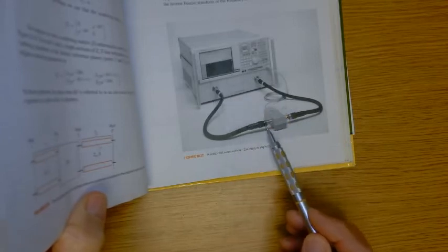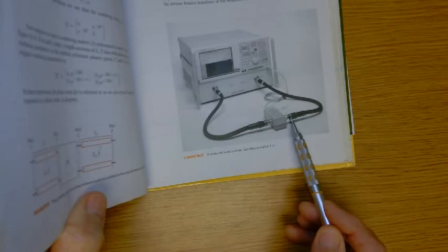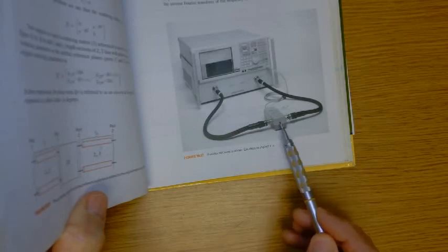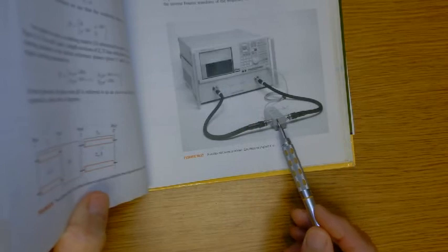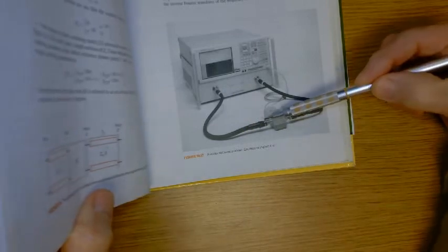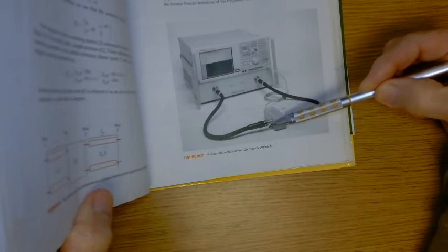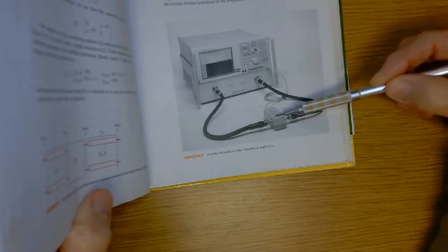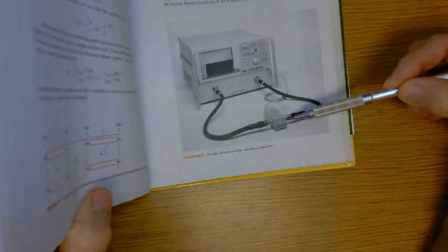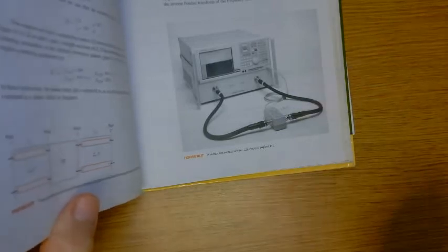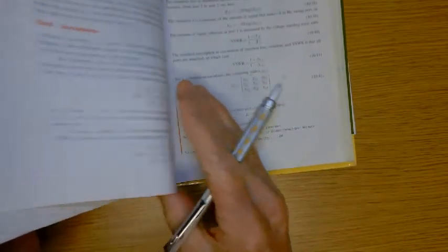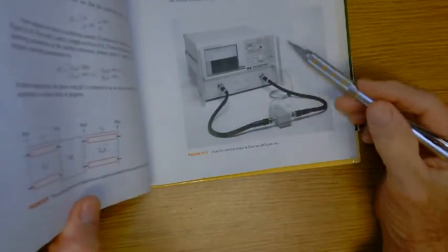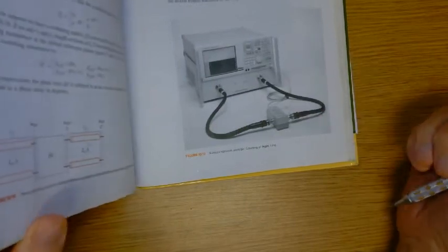Once it has all that data, you hit done cal, and then when you put your device in there, it'll actually measure and present the scattering matrix associated with the device itself at the ports looking into the device. So there's a calibration process that has to take place there, and Stu describes that. There are plenty of network analyzers around the department, so hopefully you'll have a chance to use those while you're progressing through your career.